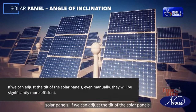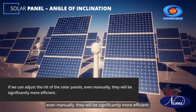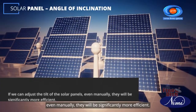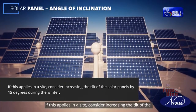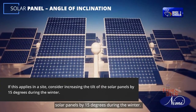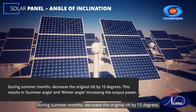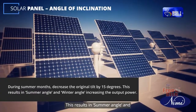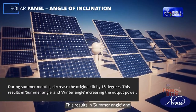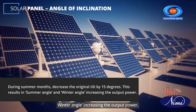If we can adjust the tilt of the solar panels, even manually, they will be significantly more efficient. If this applies in a site, consider increasing the tilt of the solar panels by 15 degrees during the winter. During summer months, decrease the original tilt by 15 degrees. This results in a summer angle and a winter angle, increasing the output power.